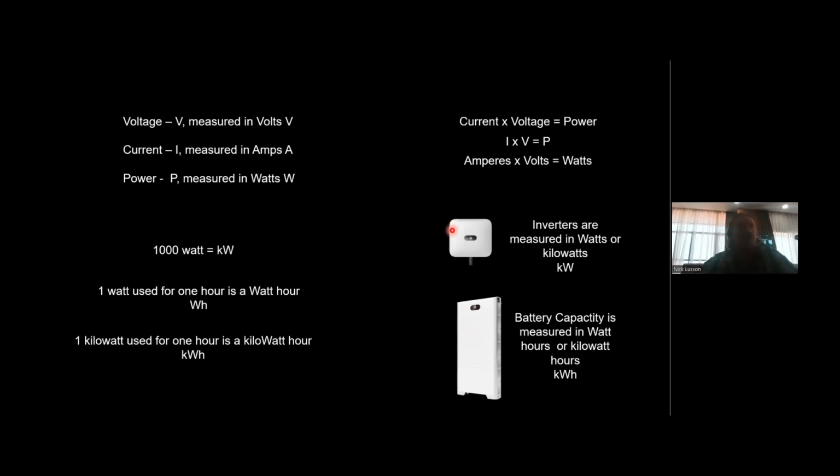And the same is true for the inverter. You cannot have a 5 kilowatt hour inverter. The inverter is kilowatts and the battery is kilowatt hours. So I'm just going to repeat myself because I think that's very important for learning.